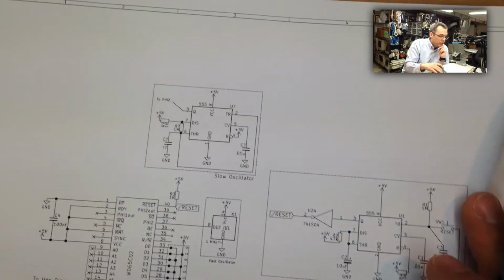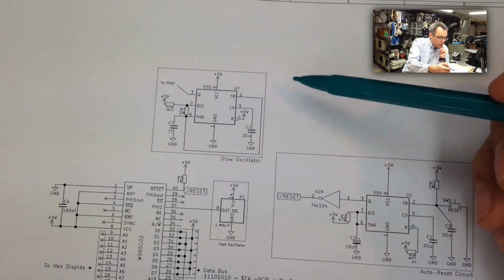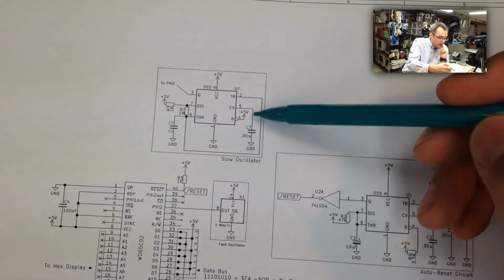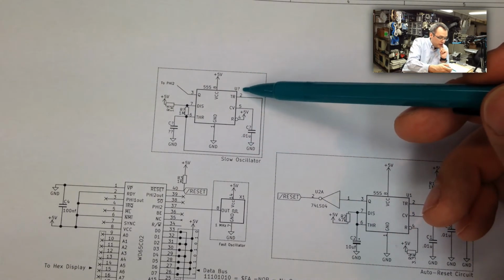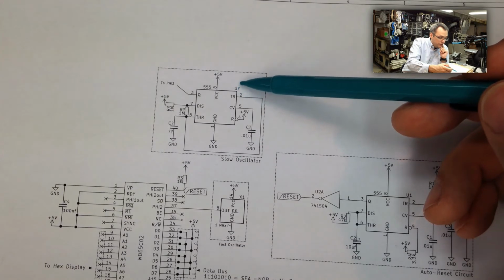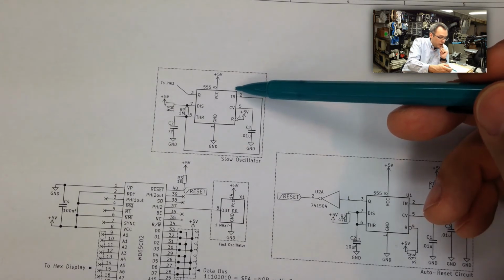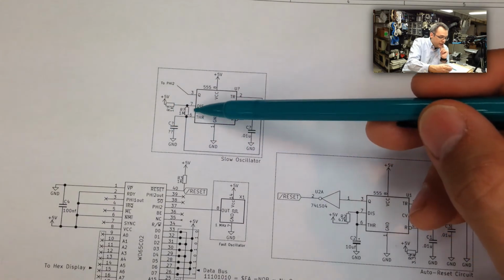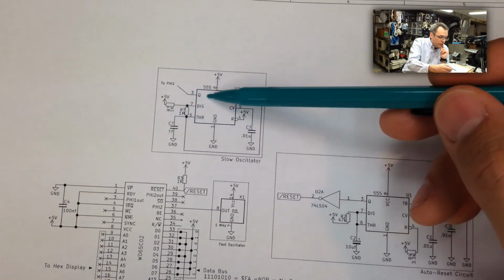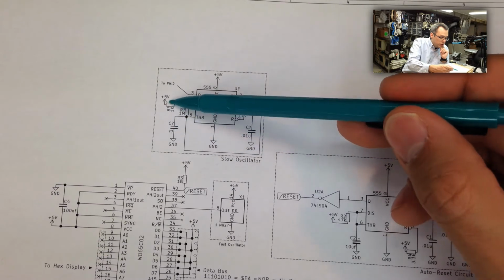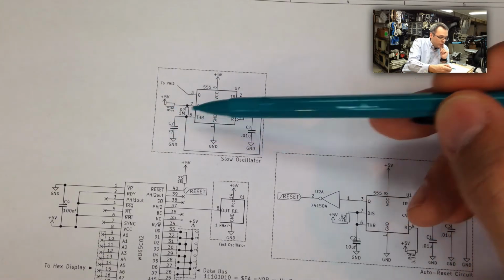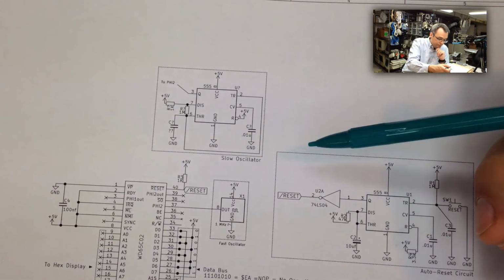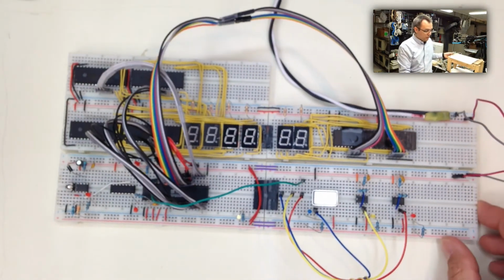Of course, we have our oscillator up here as well, which we described. This is just a very basic 555 running in monostable or astable mode with these two devices right here, basically timing this with whatever variable resistor value and capacitor value I wanted to put in there to get the frequencies that I wanted. And that is all we have to it right now.